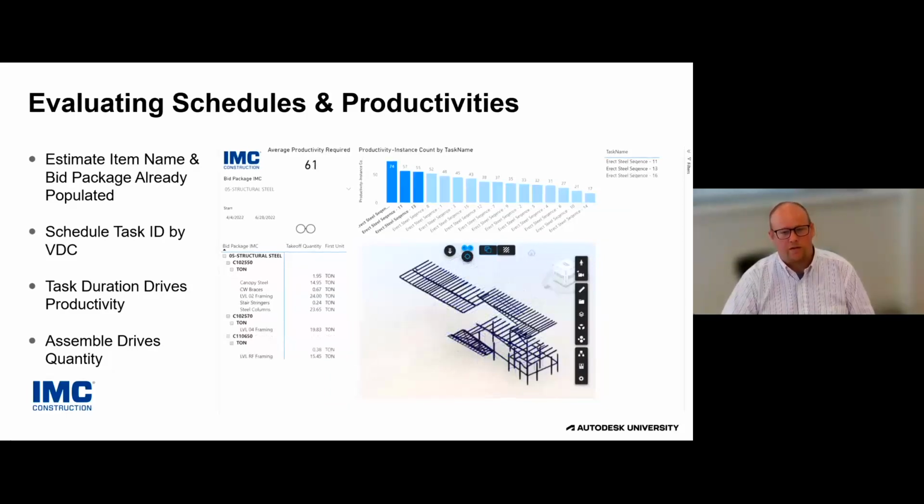you'll see a third sequence. So the 57 and the 55, those two, yeah, they're very similar structural steel framing for slab on decks. There's no columns. Those two, yes, they should have roughly the same productivity. But if you look towards the very bottom right, what we ultimately decided to do, we wanted to separate the canopy as a separate sequence, make a separate schedule activity, and really start to say, all right, that can be pulled away from the critical path. We can do that at a later date, just make sure the connections are there and available and really start to separate it out, like I said, to make sure that we deliver that predictable results on the schedule. And I think that is my last use case.